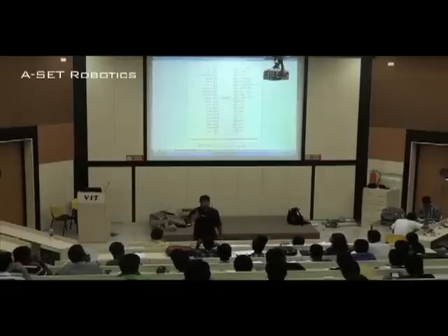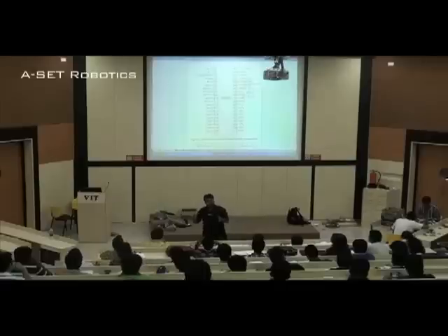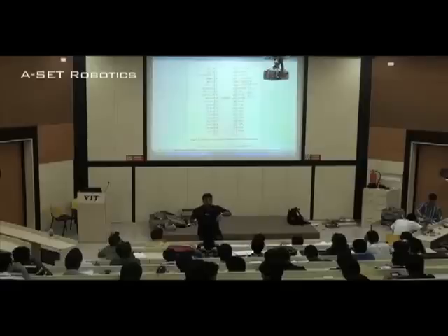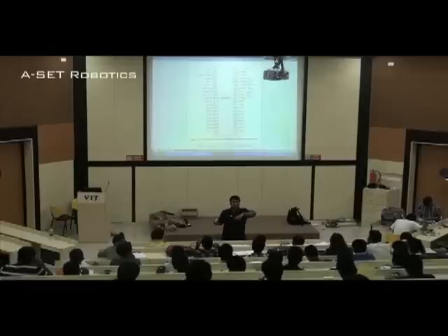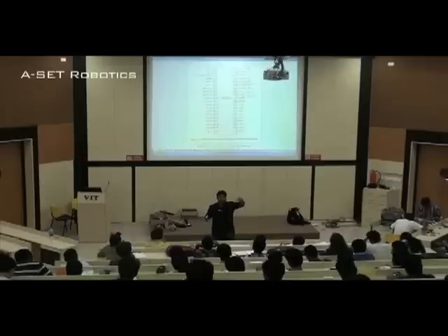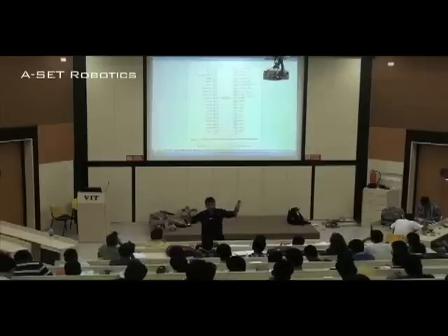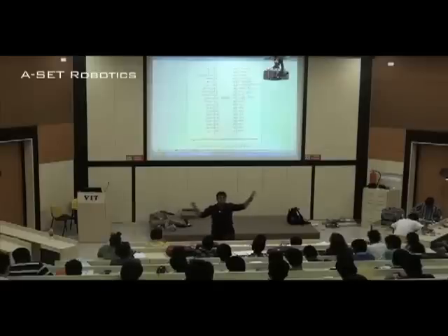Ready. Whenever we want data, or whenever we want to write data to a memory, it's not necessary that the memory is of the same speed as the microprocessor. So whenever it asks for data or asks to write data at a specific memory location, that memory device might not be ready at that point of time. So it will say, hey, wait for some time. And this ready pin would be set to 0. That means I am not ready. The memory is not ready.